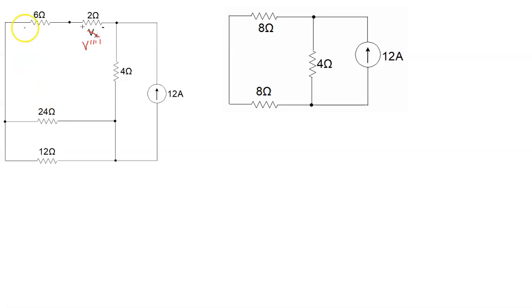Over here, remember there was a 60 volt source that we shorted out, and that took out the 20 ohm resistor, so that part on the left is gone. In the middle here, we took out the 5 amp source and the 3 ohm resistor branch, just like we did in previous circuits, because it's open. And so, you should be able to visualize now that from that original circuit, with the pieces that were shorted and opened, we came up with this.